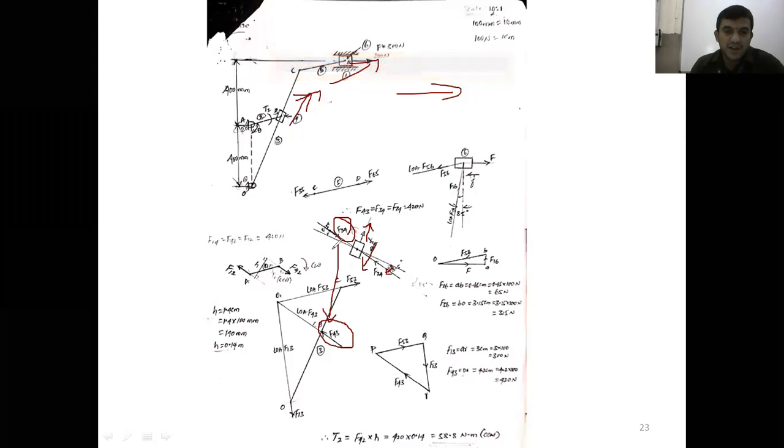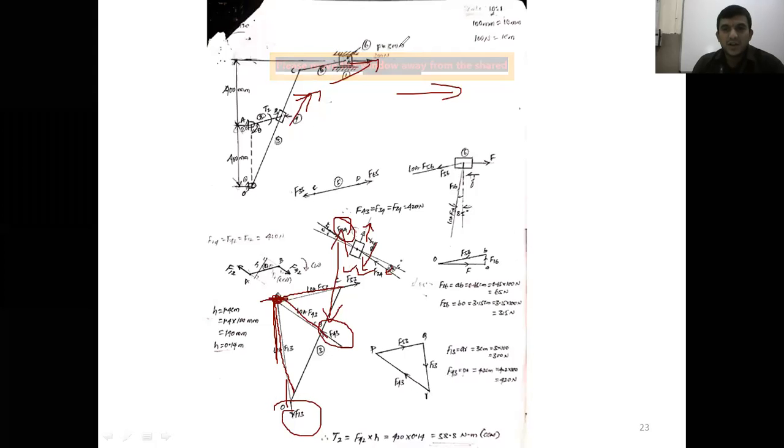Again, draw a line which is normal to the displacement of the slider. From that normal, draw an angle towards the small f, the frictional force, 8.5 degree. Now that gives the line of action of F24 and F34. Once you know the line of action of F34, that is equal to the line of action of F43. Now F53 we already know, both magnitude and direction. Extend that line and extend this line of action of F43, those two meet at a point. O1 you call it, since O we already used. Then join O to O1. That gives the line of action of F13.